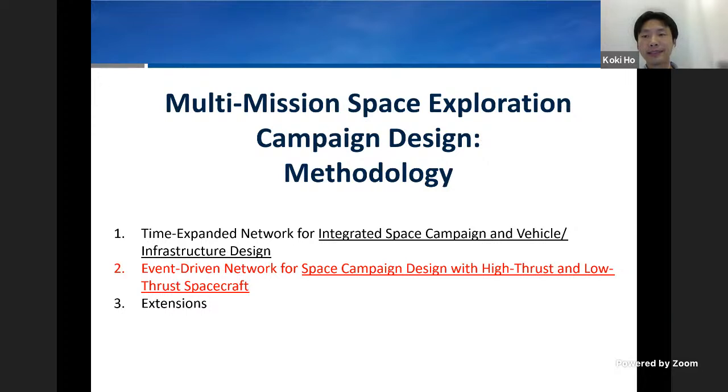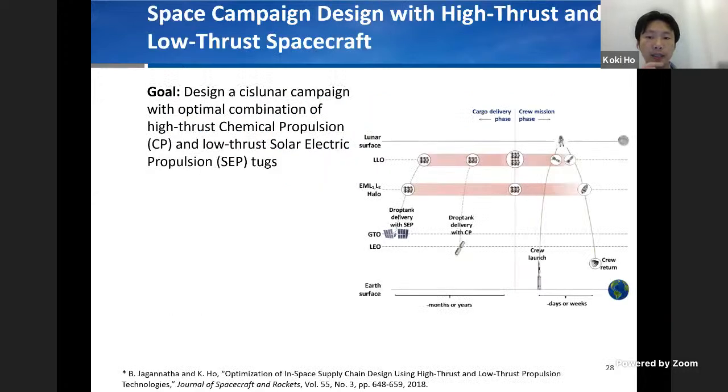But for low thrust, it's not that simple, as you may be aware. For example, with a constant thrust propulsion system, the time of flight and the propellant you need will really depend on what payload you carry. With the same propulsion stage, if you carry a very large payload, you will follow a different trajectory than if you carry a very light payload, assuming constant thrust, because the acceleration will be different. So the low thrust trajectory is a completely different problem from how you handle the high thrust case. So that is the second problem.